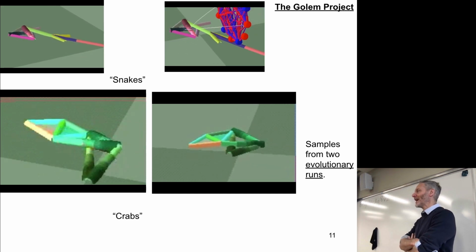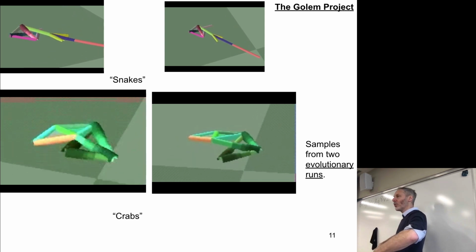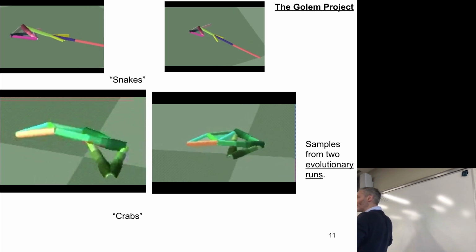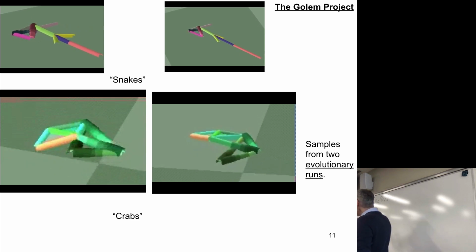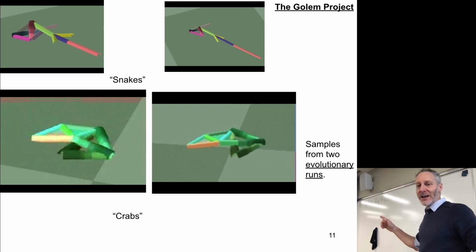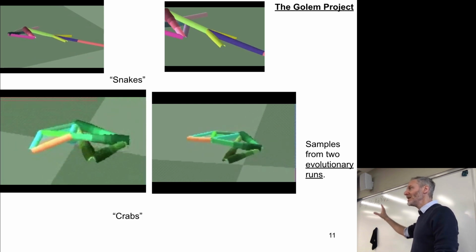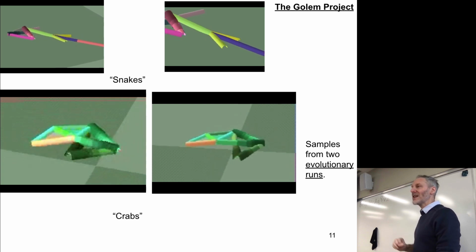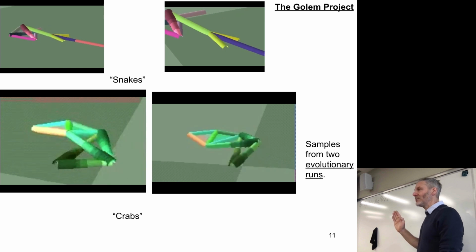Remember our discussion about legged locomotion? To be statically stable, you have a polygon of support on the ground, and your center of mass has to stay on top of that polygon of support at every point. It may not look like it, but this simulator was actually made by hand, and they constrained the speed and strength of the motors in such a way that it's always statically stable. It's a little tweak of this simulator, which we don't have too much time to go into.